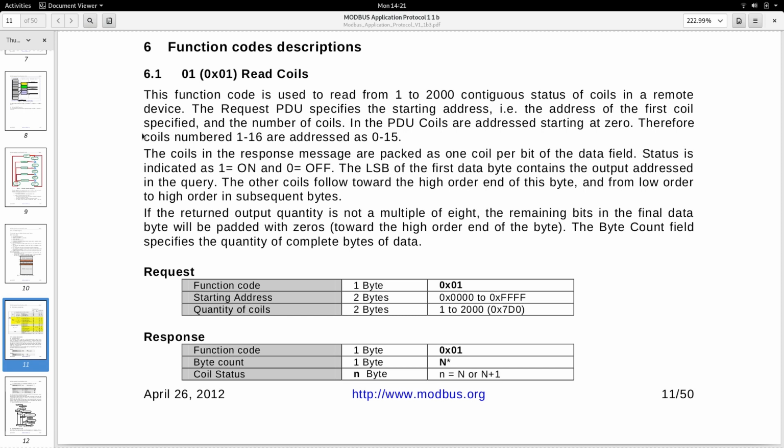So if you had a light switch or a light controlled by a relay, is the light on or off? And the MODBUS standard is described in this document as a client-server architecture. I don't think it is strictly client-server, because that's for a different type of thing. This is more of a master-slave area, where there's one master on the line sending out requests. So in this case, it can send out function codes, one of which is, I want to read the coil status, and I expect a response of 1 if something's on.